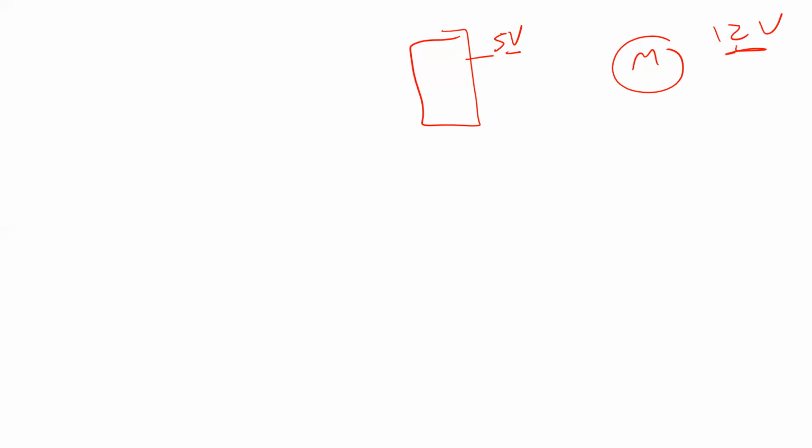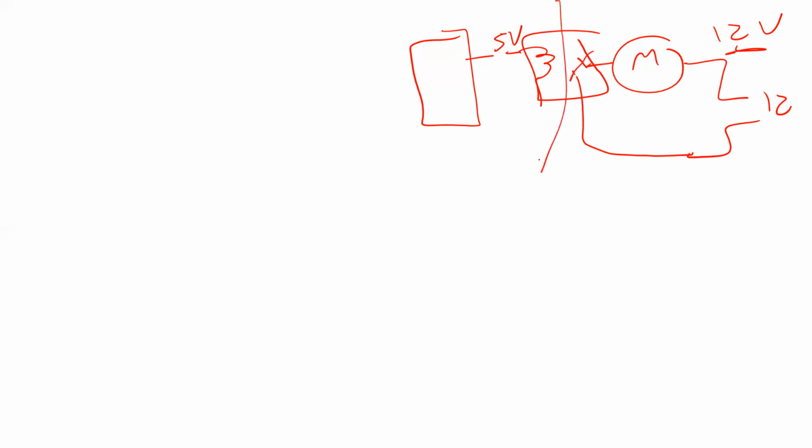Guys, I just gave an example. I said if I have an AC voltage, but that doesn't mean I have to use a relay all the time for AC. It's not like that. For example, I told you here we cannot output more than 5 volts. If I have a motor and this motor needs 12 volts, in this case you can still use a relay. The 12 volts is here, and here you can connect it to a switch, and you can still use a relay. You can do that with 12 volts. Yes, why not? Because this is a separate circuit. You got what I'm saying?